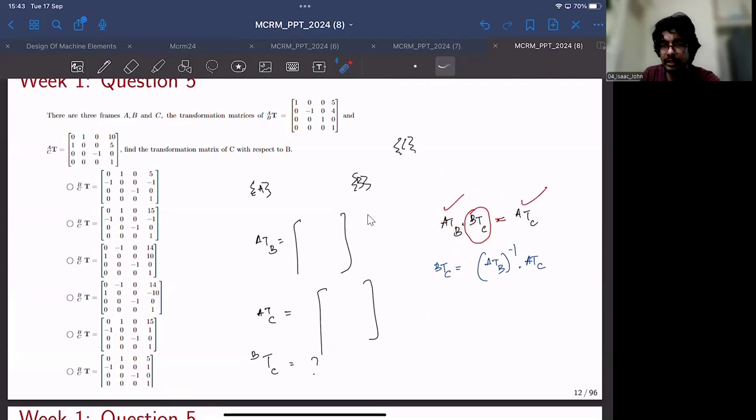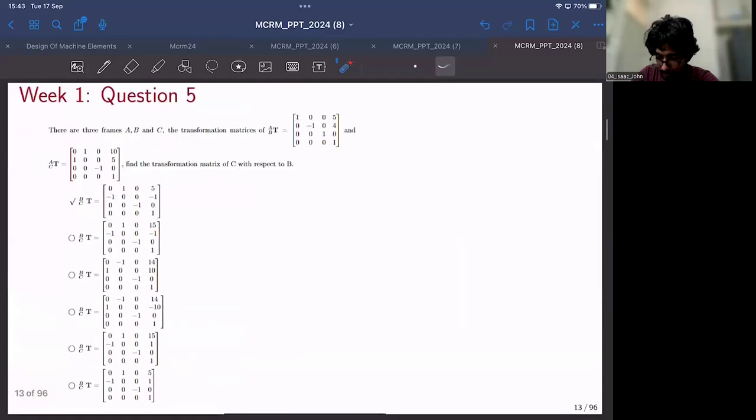Fixed or mobile frame, is it not required? No, it's not required, because mostly we use this for DH transformation. And in DH transformation, we always mention it with respect to the current frame, everything is eventually transformed into the current frame. But when it comes to purely rotation, when you are only dealing with rotation matrices, then it has to be specified with respect to which axis you will be rotating. But transformation in general will be mostly defined with respect to the current frame. That's about it. So that is how you would solve this problem.